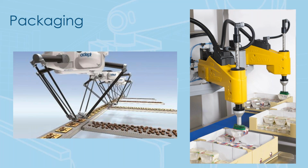It's a very common high-speed application that we see typically in food packaging, as these parts are coming out of an oven or some other type of food processing process. So that's a great application for a Delta robot, since it's up above, it's designed to be mounted above conveyors. And you could also do this application with a SCARA robot. And on the right, we're seeing another packaging application where we're picking parts off a conveyor and placing them in boxes.